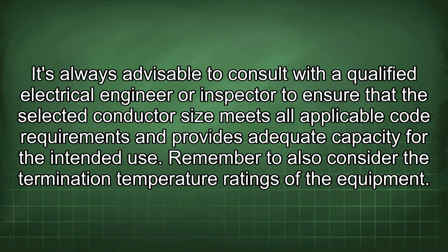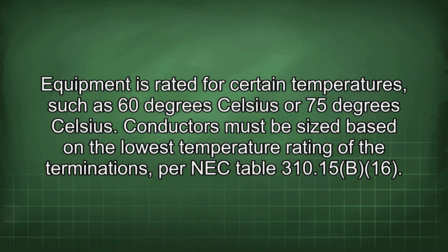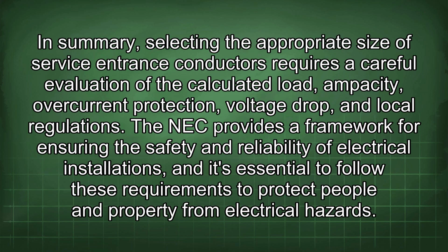Remember to also consider the termination temperature ratings of the equipment. Equipment is rated for certain temperatures, such as 60 degrees Celsius or 75 degrees Celsius. Conductors must be sized based on the lowest temperature rating of the terminations per NEC Table 310.15(B)(16). In summary, selecting the appropriate size of service entrance conductors requires a careful evaluation of the calculated load, ampacity,